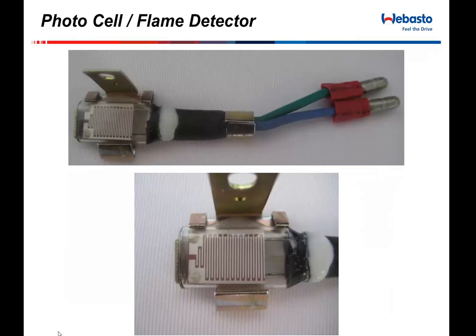Once that piece loses its internal vacuum, it will stop working. If that part fails, the symptom of the heater is very easy. The heater comes on, it runs for 20 seconds, and it turns right back off. That's happening obviously because it can't see any light and the product is not working.